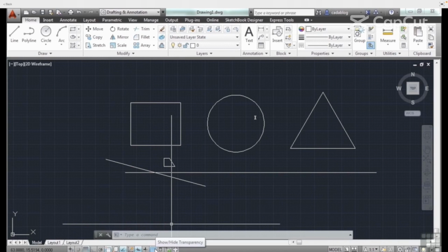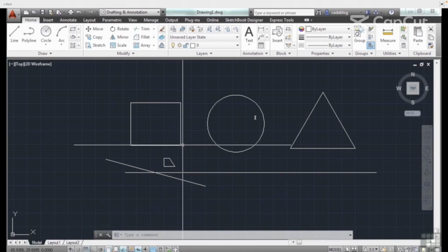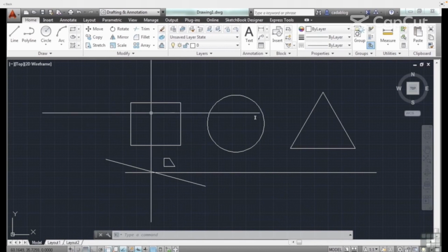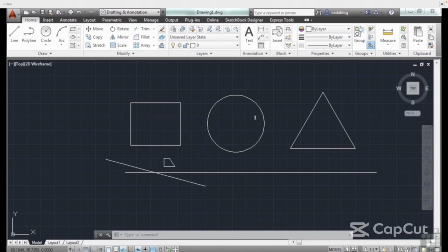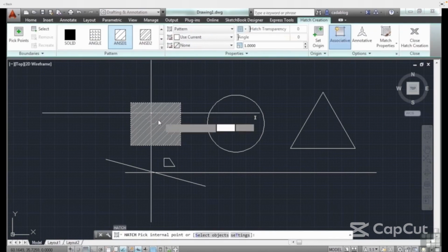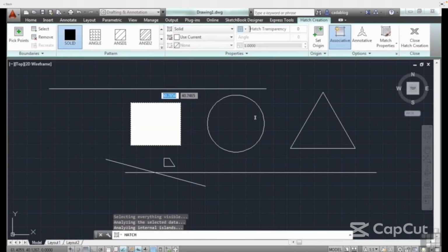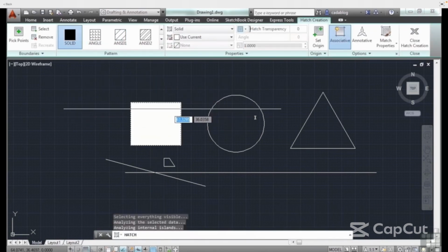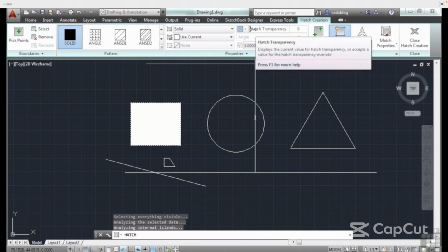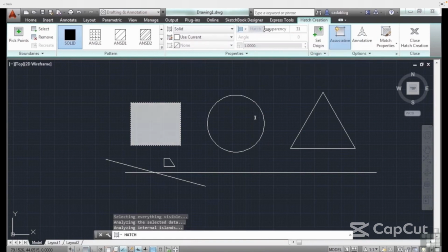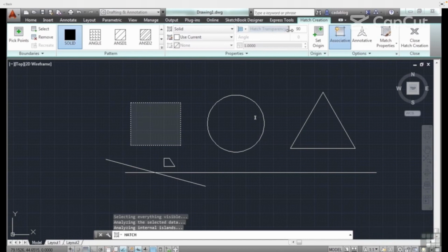This is with the transparency setting. Again, another function we'll talk about later, but you can make objects transparent, translucent, opaque, and you can see through them, especially in a hatch. That works quite well. So if I have this solid, it's at full transparency, meaning it's set to 0, meaning it has no transparency at all. It's full solidness. But as I increase the transparency up to a factor of 90, you can see it kind of fades, and I can see things through it.